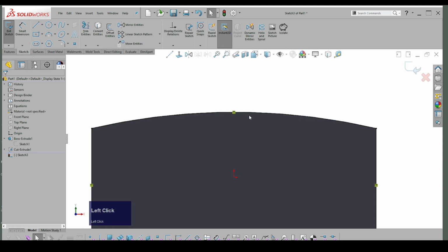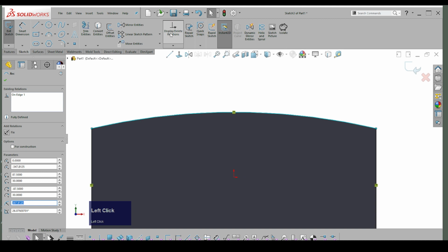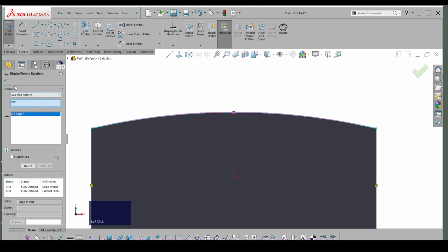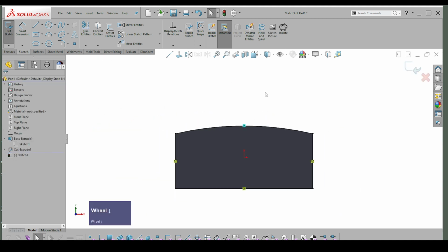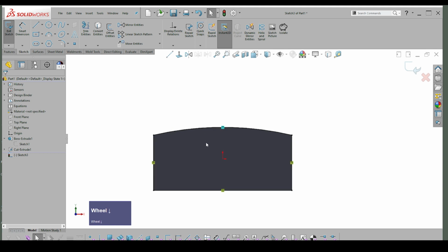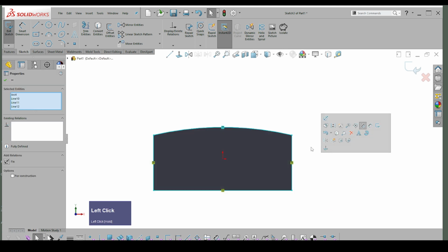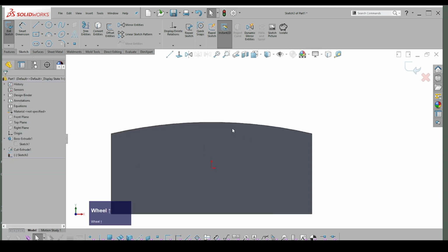Sketch environment, we're there. Display units, on edge, right, so it's an on edge relation. This is not quite what I want, because this is going to be very difficult to control later on, because that on-edge relationship makes it difficult. I'll show you why now, because what I want to do is offset that